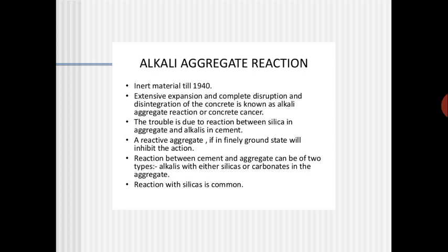We cannot say the alkali reaction is only with the aggregate. The silica is present in the aggregate, in the cement, and in the sand also. So when this alkali, that is sodium hydroxide, reacts with the silica content present in the aggregate as well as the cement and the sand, normally silica gel is going to form.